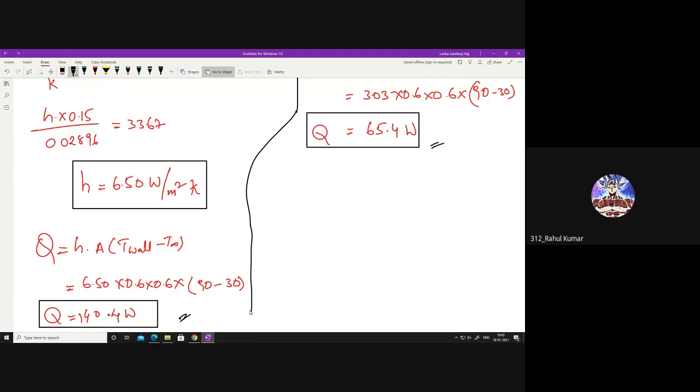When the surface is faced down, the heat transfer will be very less. So while designing your components, especially these electronic components for your laptops and computers, the kind of orientation that you put for this natural convection case will hugely influence the heat that is coming into the plate. So that's why it is always advisable to keep the hot surface in the downward direction. So the heat transfer is actually very less compared to your hot surface up case. Okay. So how about your vertical case?